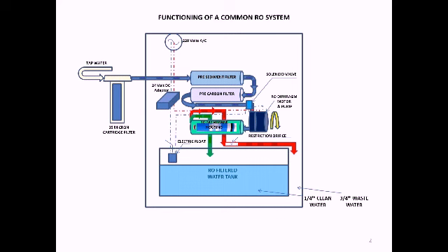Generally in a household RO, with respect to the 25 micron cartridge filter water TDS to the RO filtered water TDS, there's a difference of roughly 1/10. So supposedly tap water is roughly around 700 TDS. So after filtering from the RO, you would get roughly around 60, 65, 70 TDS. So that is the kind of filtration it does.